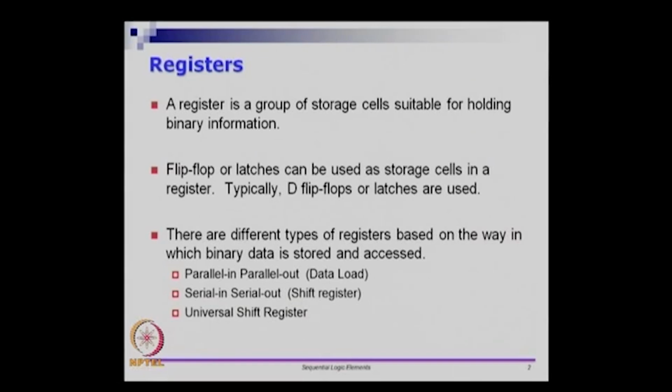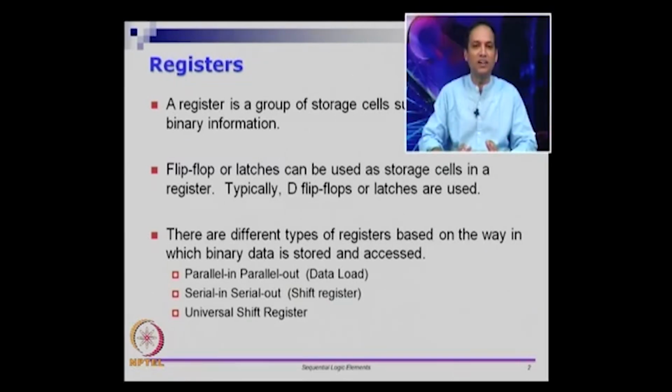If you look at a toggle flip-flop, then it is a control condition: when toggle is on, toggle the value and so on. What D does is it just stores whatever is given as input when the clock arrives. So this is a fairly simple flip-flop to understand and conceptualize, and I am going to use only D flip-flops in my material here. Once in a while I will also talk about T flip-flops. If you go back to your textbooks, you may also see things like JK flip-flops and so on, which I am not going to address in the course.